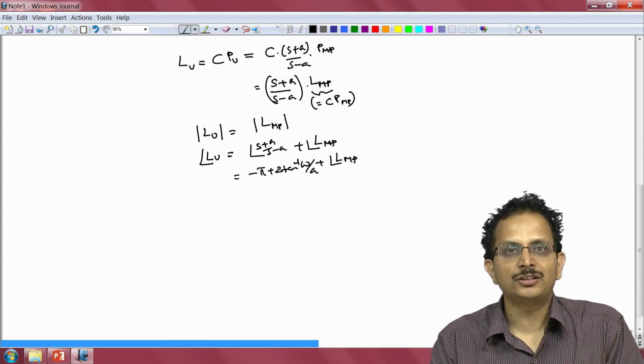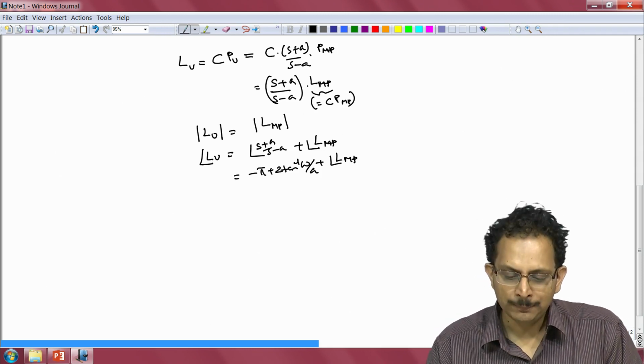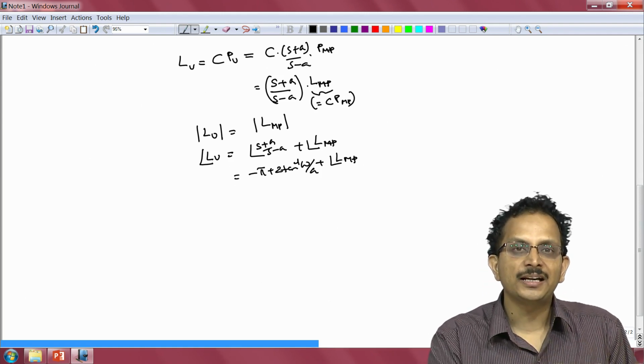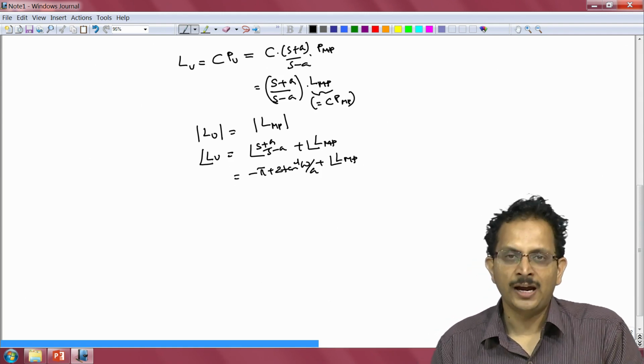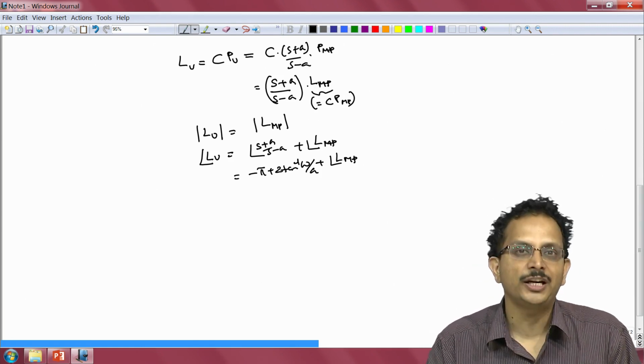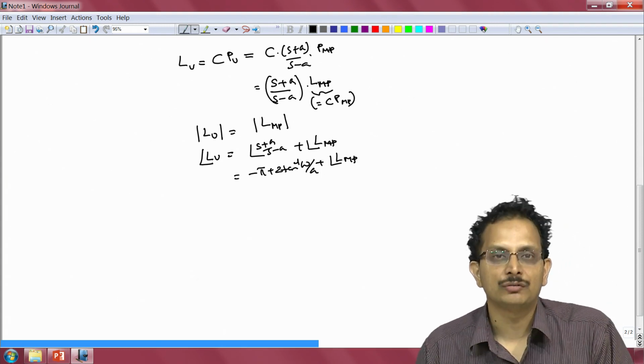So let us sketch the Bode plot of our unstable loop gain when our magnitude characteristic has an integrating characteristic at low frequencies, and see what kind of confusion the phase characteristic of such a loop gain could cause in our effort to determine the stability of the closed loop system.